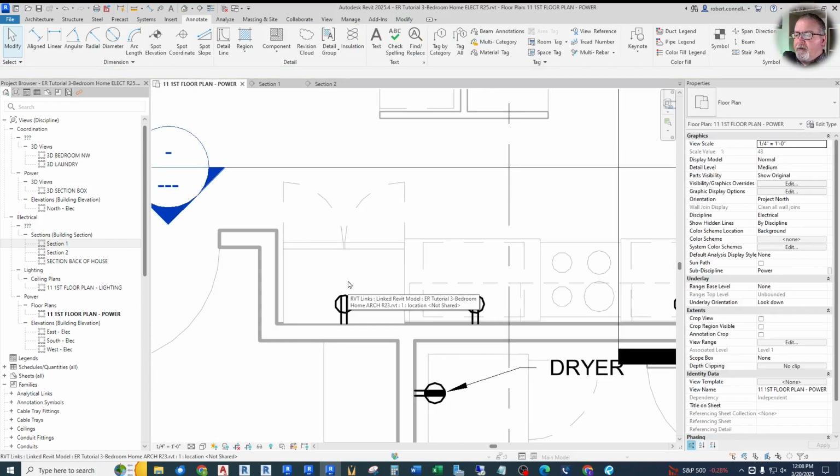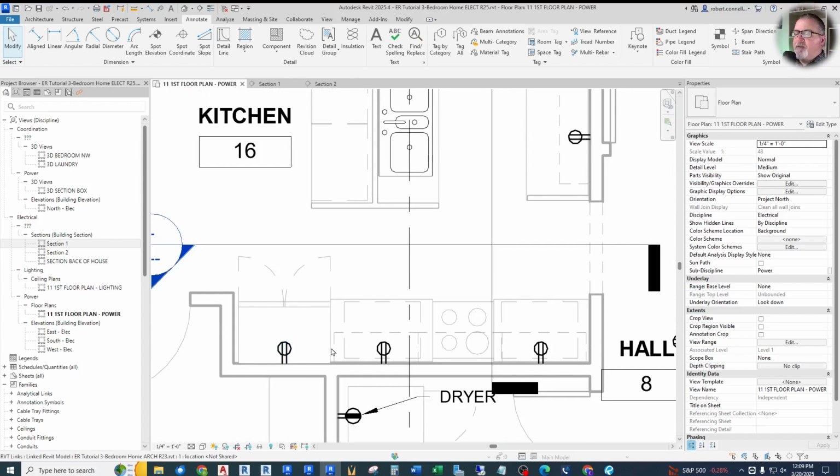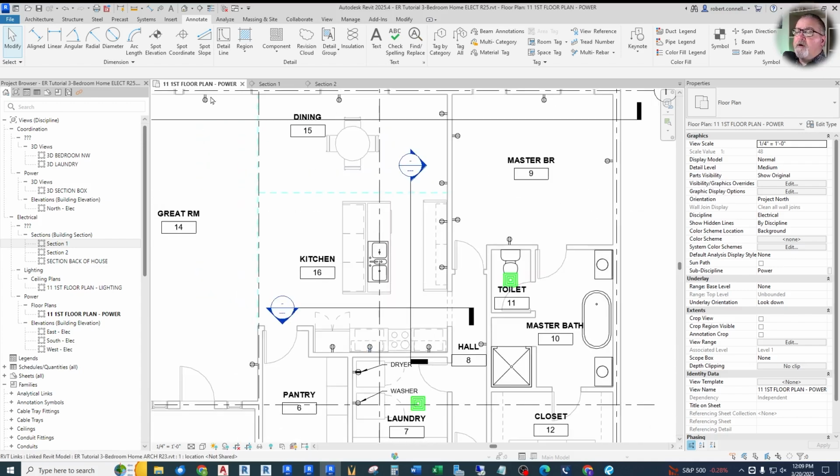Another thing about the NEC is it's going to require GFCI or GFI, ground fault protection, on many receptacles in the kitchen. So you'll need to follow that. Now you may want to indicate GFCIs here, or you may include those requirements in a list of notes or specifications. So in this case, I'm not going to be showing it for all of these. I'm going to let my separate written specifications remind the contractor to put GFCIs and arc fault receptacles, tamper-proof receptacles, all of those code things within some notes, not actually on the plan.